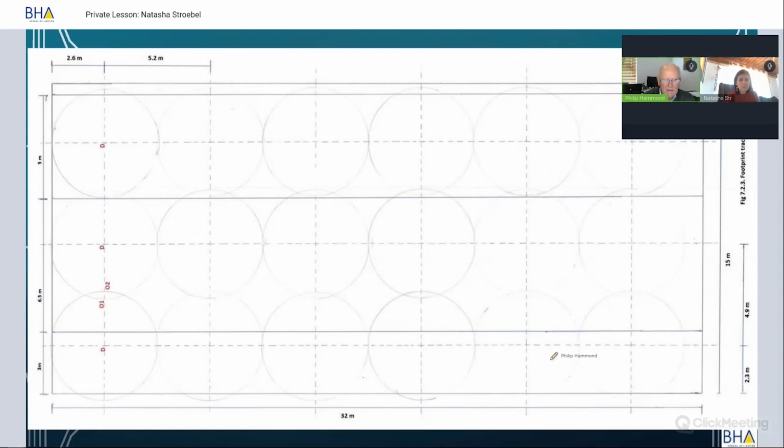And once I've finished doing that, I've now got a nice map of how many light fittings I'm going to use. So now you see I've used my graph paper. I've got all those dimensions in from my layout, and you can see I've already worked out what all the light fittings are. How have you done those circles there now?